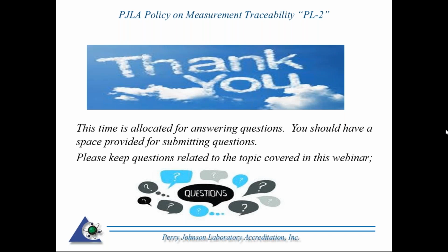I'm not really sure. You're asking about starting to implement decision rule on routine performances. So the decision rule is something that's documented on a calibration report. This is something that your customer needs, and that's just if you're making a statement of compliance. If you're saying pass, fail, in tolerance, out of tolerance, then you have to worry about the decision rule.